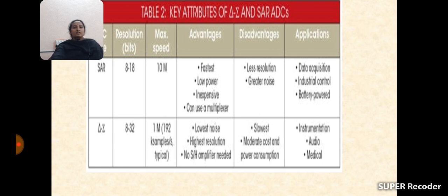But these analog values cannot be understood by the system. Also for humans, if we get it in digital value, then it is very easy to understand, but in analog it is somewhat difficult to understand. So there is a conversion of analog into digital with the help of the successive approximation converter and also the counter method.